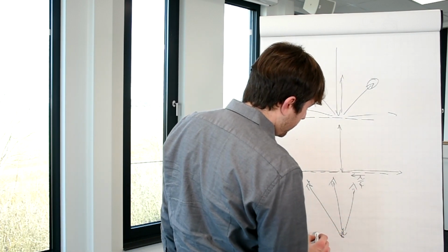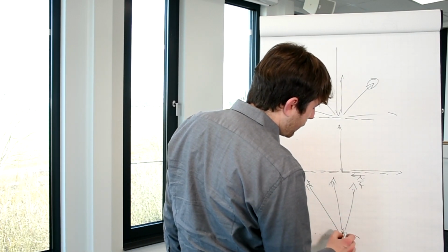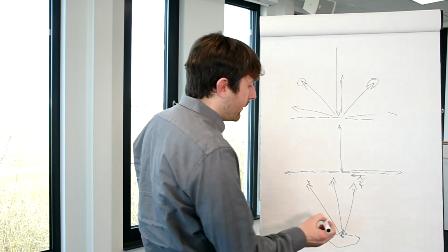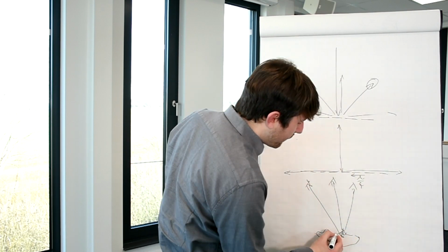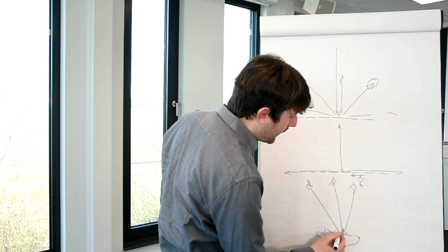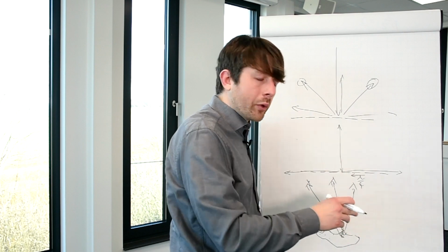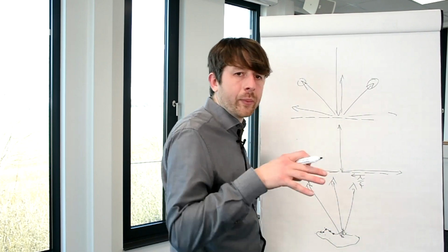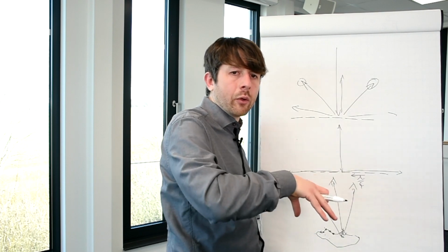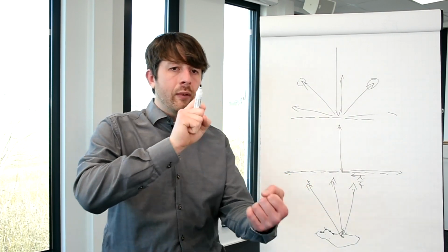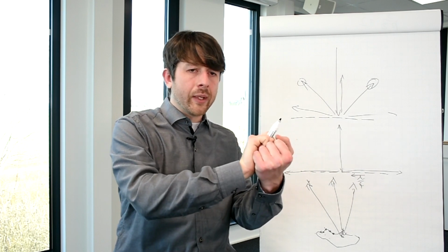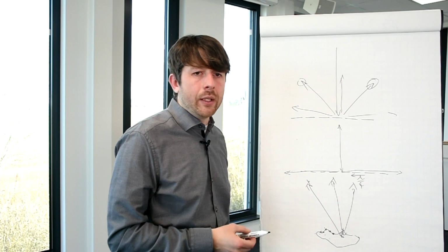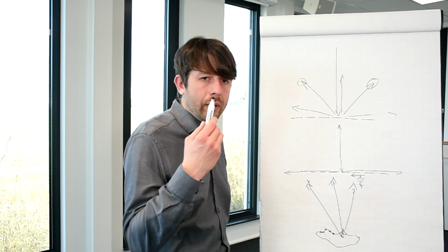If I have an object which is arbitrarily distributed, and I want to get an image of that, then I'm basically trying out different positions, compensating the phase, and focusing on different points. I focus on this point, this point, this point. That forms the image. So a triangulation or multilateration just gives me the position of some object, while back projection gives me the shape.